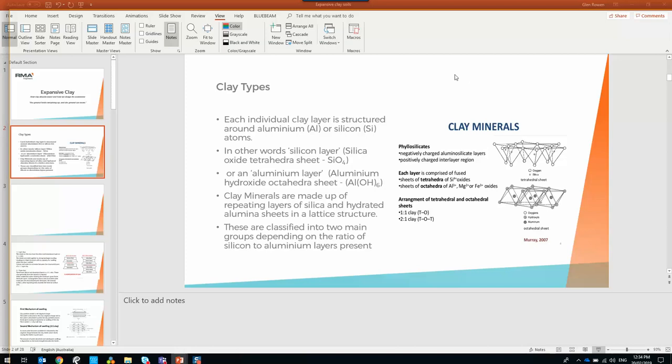Now, you'll see a lot of soil reports and they predict Ys, which is surface movement. The big thing you've got to understand with the Ys value that the soil guys report in a soil report is that it just assumes normal moisture changes due to normal climatic conditions. Like, the location is important. If you've got the same clay on the coast where it rains every second day, it might have a Ys of 70. Same clay out of Dalby, 130, 140.